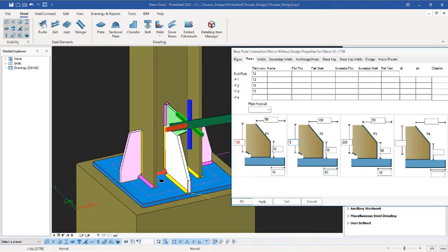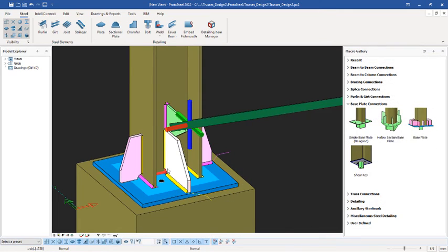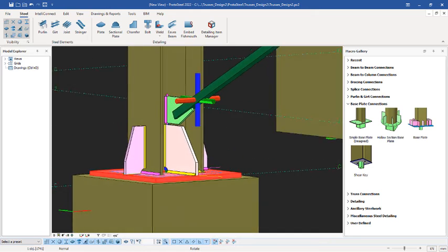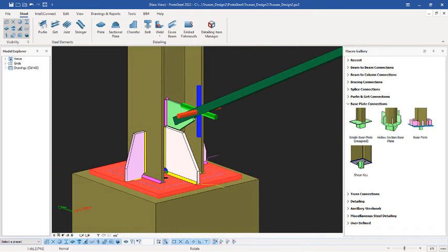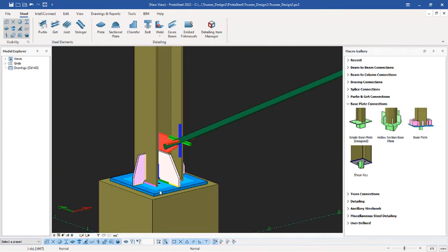So you can have all the plate thickness be 180, or you can reduce only the center one, which is this one. But I prefer to reduce them all together, just like this. Click on apply, then click on the OK option. Alright, so now if you update it, you can see there's a little space between this gusset plate and the stiffener right there. So this is good.